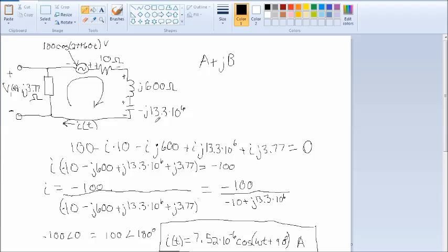And we just found that at 60 hertz, we can basically call this a purely capacitive load, which means that our angle, our phase shift, is 90 degrees positive. If it was a purely inductive load, it would be negative 90 degrees. If it's a purely real or resistive load, then our angle will be 0.